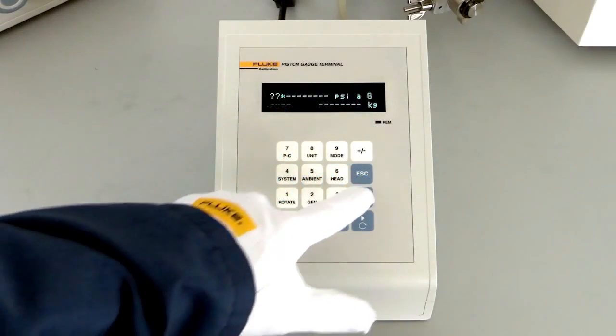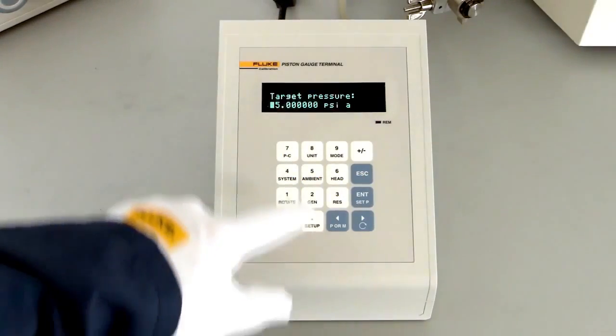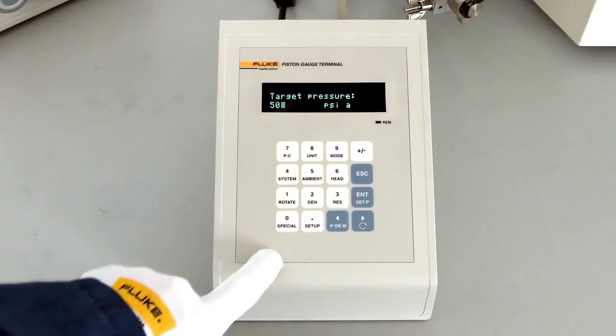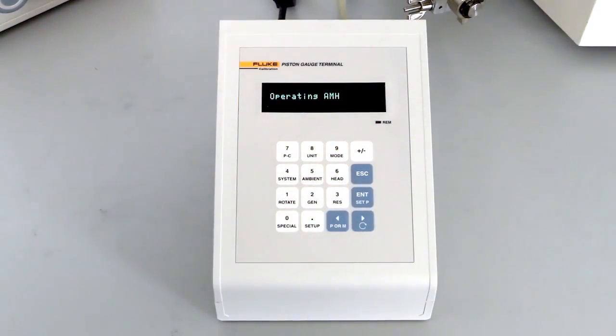The first extreme is to measure each variable that impacts the pressure and perform a full calculation of the fundamental pressure equation. This is the approach used on high-end piston gauges, like the Fluke Calibration PG7000 series. By using this approach, with the right equipment, it is feasible to get the lowest uncertainties possible.